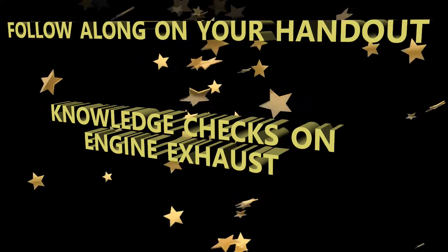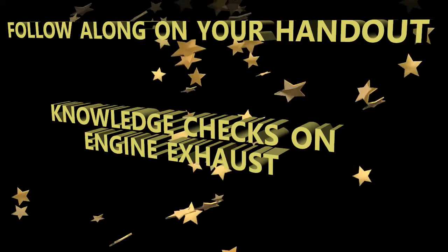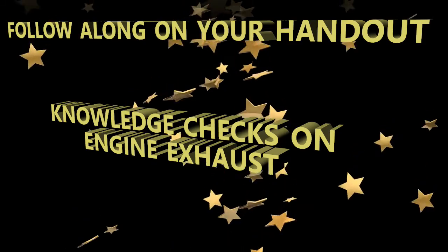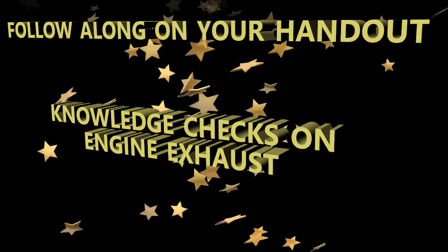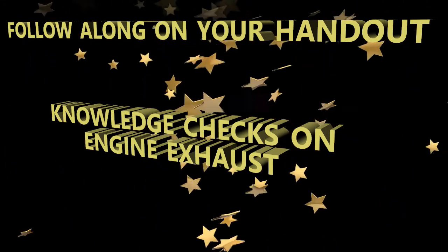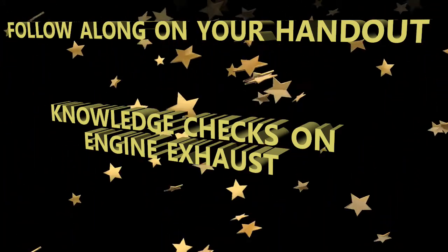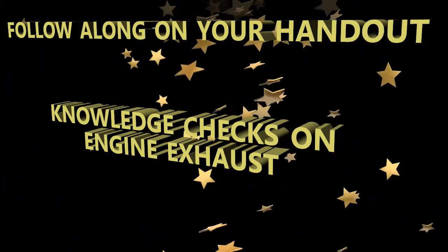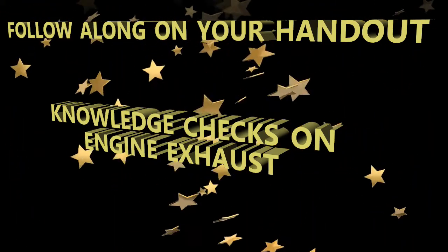Number 16, one of the functions of the HCU is to control and regulate the speed of the blocker doors. Right, we're not just talking about position when we talk about actuators and giving instruction, but also speed. So position and speed. One of the HCU's functions is to regulate the speed of the blocker doors, so the answer is true.